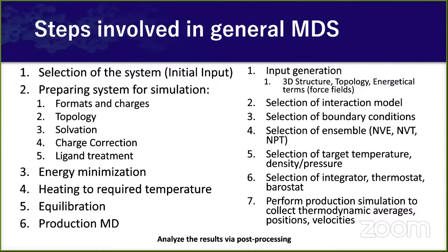So when you have a cubic box and the XYZ periodic boundaries, essentially you have 26 copies of the same system all around it, making a total of 27 images. That is if it is cubic, but cubic is just one type of box we can have for simulation. We can have octahedron, we can have a sphere or shell, and many other shapes can be used to create the simulation box.